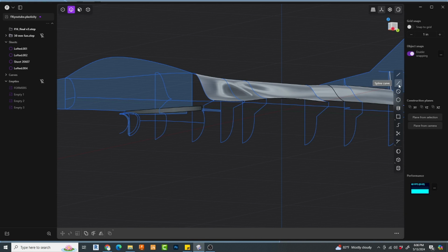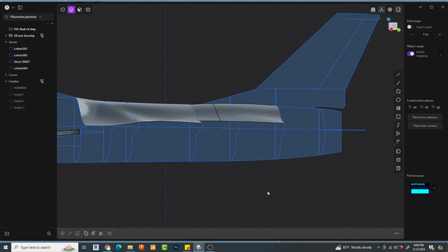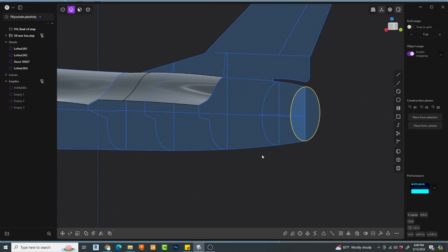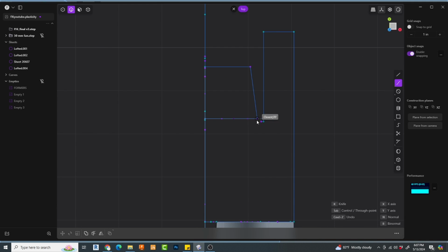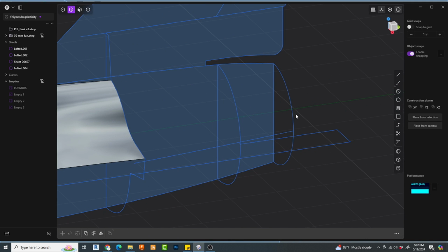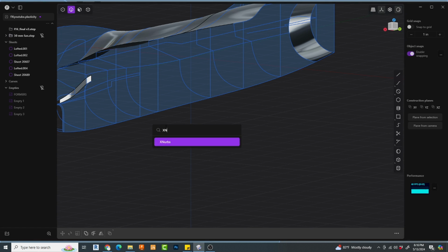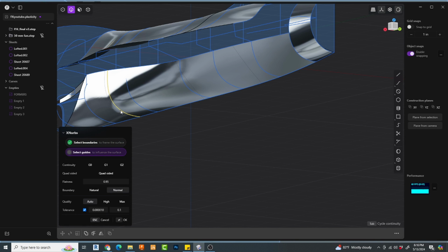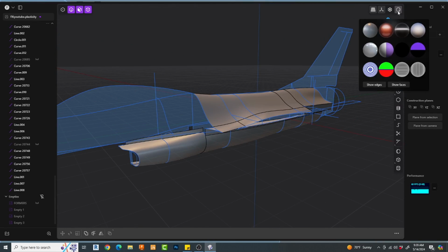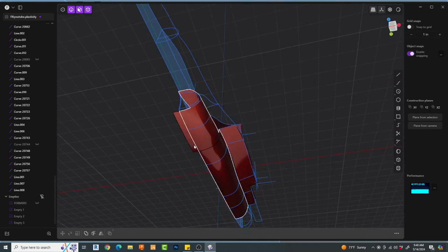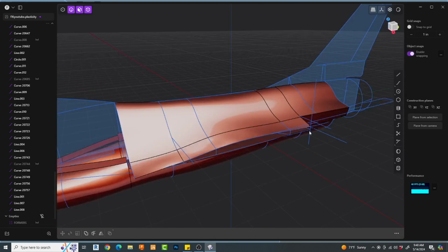I'm redoing this bottom rail here. Notice that I'm using spline curve, not control point spline. I'm using the Nurbs command here, and I'm using the formers as guides on this. I'm going to right click on toggle render mode here because I want to be able to use a different shader that helps me to see curvature a little bit more cleanly.